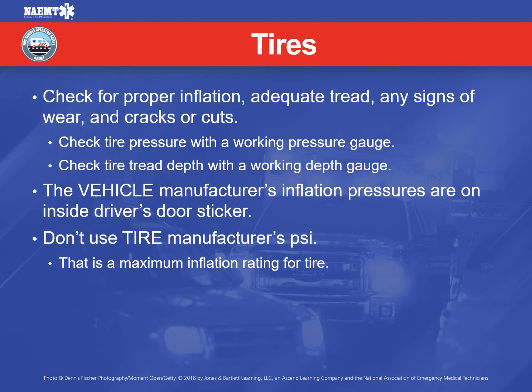Let's talk a little bit about the tires. We need to check for proper inflation, adequate tread, and any signs of wear, cracks, or cuts. Check it with a working tire gauge. Now, I use ICD as a mnemonic to help me remember: I for inflation, C for the condition of the tire, and D for the tread depth.